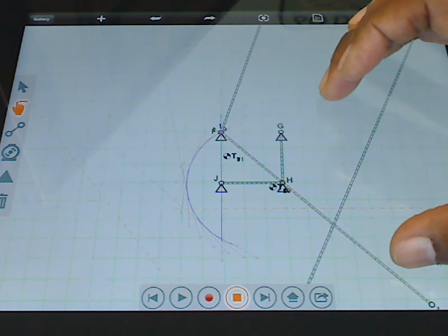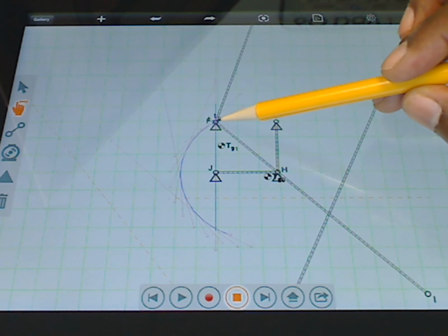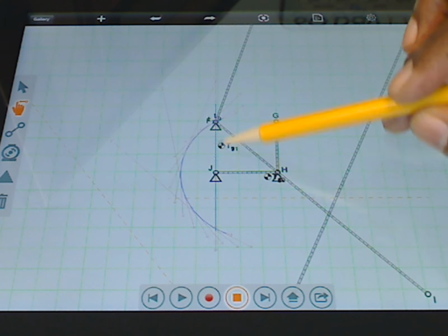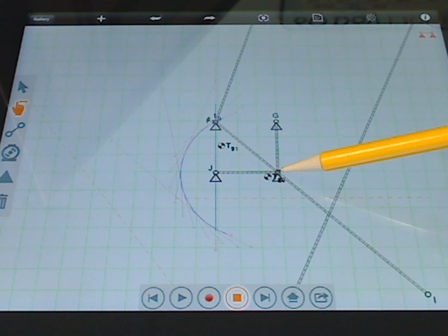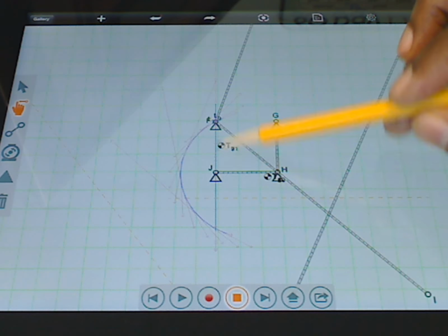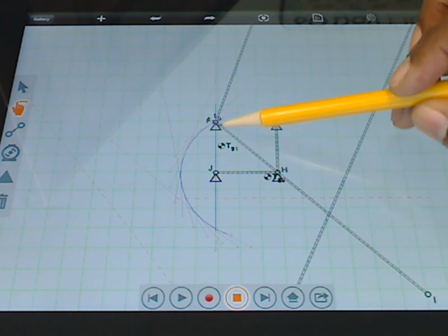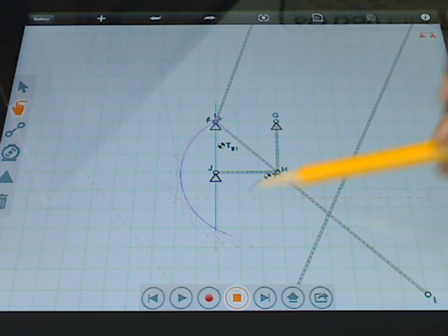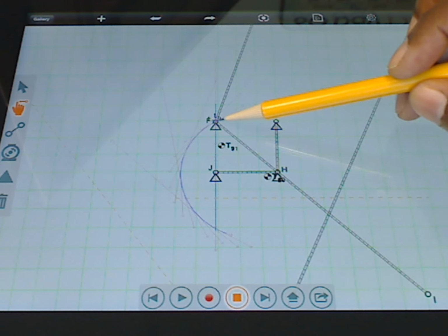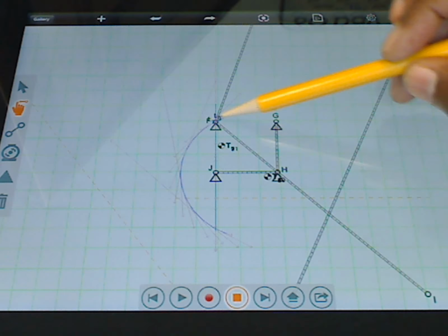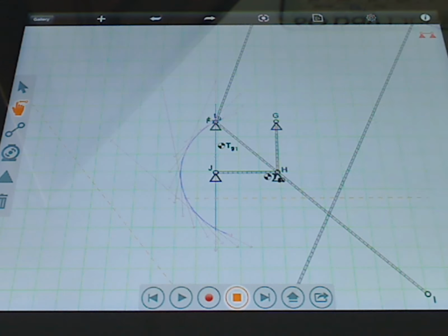What we have here is the dwell position, and we've come down and over the same amount to get a 45-degree angle. So this is about 0.303, and this is about 0.303, and we put our ground position. That's creating a 45-degree angle here, and when this comes down to its maximum stroke, that's the additional 45. So we have this output link swinging through 90 degrees of motion.